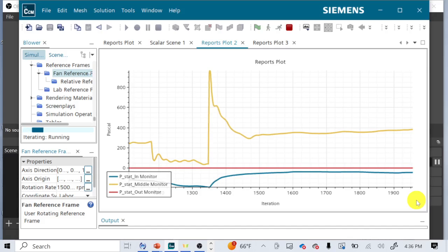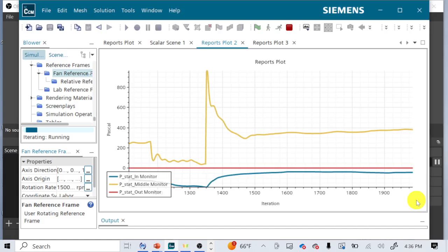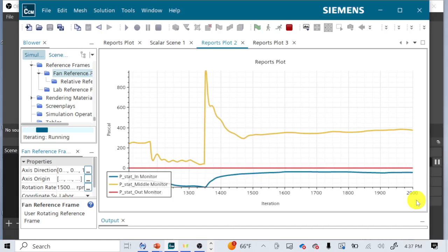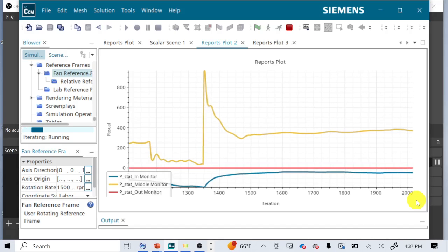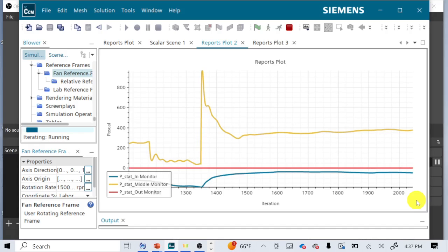Your density and your temperature are only really going to change noticeably if you have a really high power compressor or you're compressing air a lot, which some types of machinery absolutely do, which is not what we're doing here in particular. Your typical centrifugal compressor, not fan. They operate on similar principles, but they're optimized very differently. Your typical centrifugal compressor can get a pressure ratio of about 3. You can get about 3 times the pressure out that you feed into it. Your typical axial compressor gets you a pressure ratio of about 1.2, maybe 1.1, depending. You might get a 20% or 10% increase in pressure going through an axial compressor. So conceivably, for compressors or things of the like, you might get large changes in density, temperature, etc. We don't expect them here, but that might be something to look at regardless.